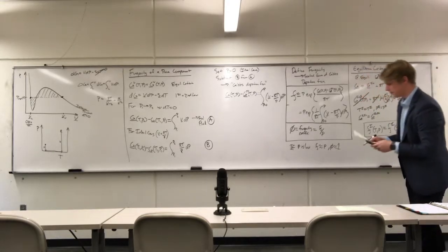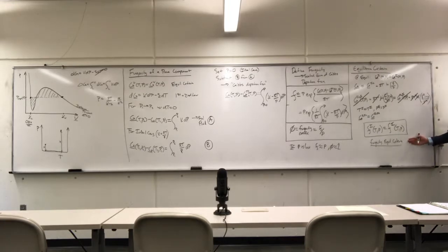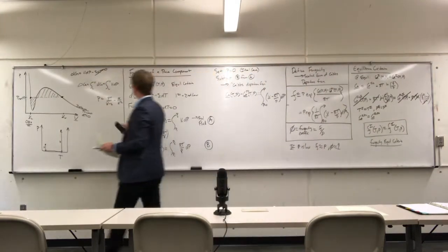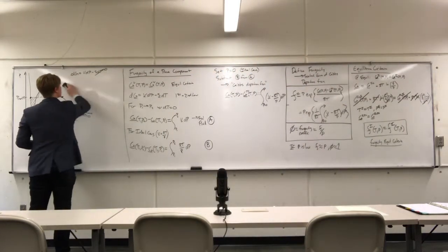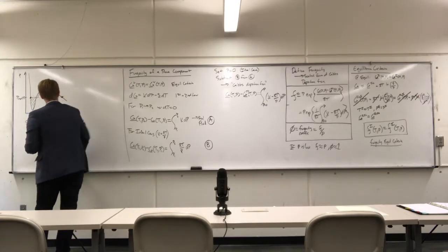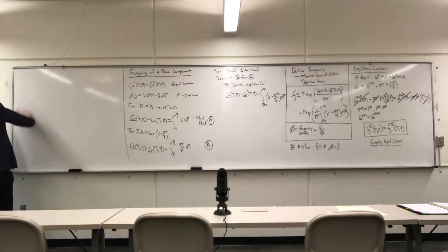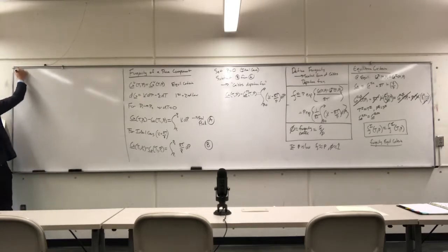So we can use fugacity to do all of our phase equilibrium calculations, and we don't have to worry about calculating the Gibbs free energy. Okay, let's talk about how we calculate the fugacity and see how we can actually apply it to solving the problems that we're worried about. Phase transitions for a single component is what we're focused on right now. So we'll start off with the fugacity of a vapor.